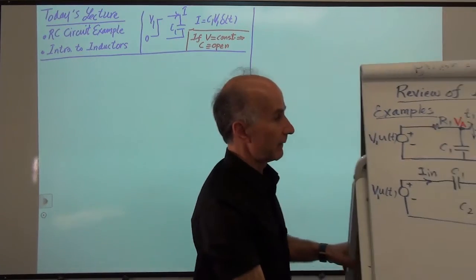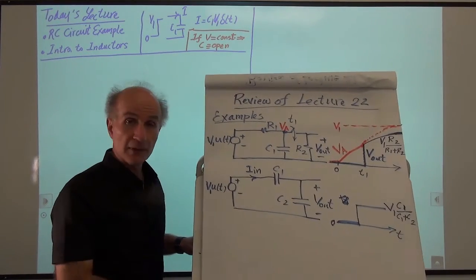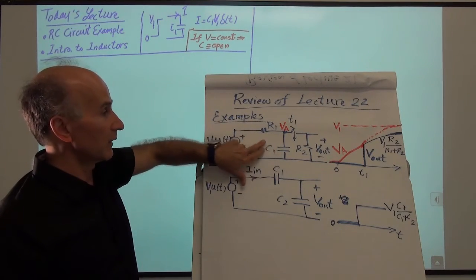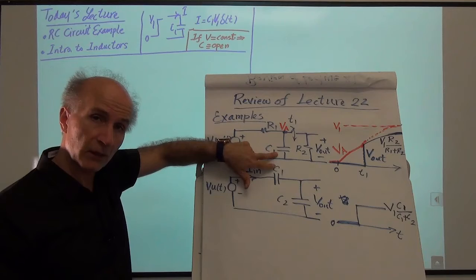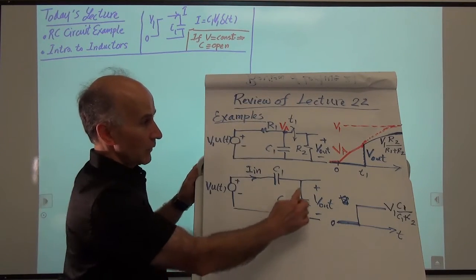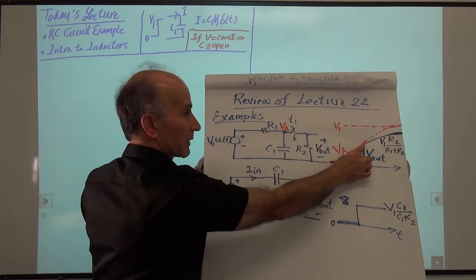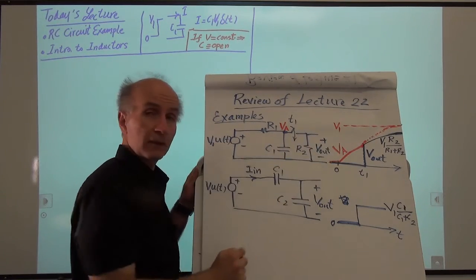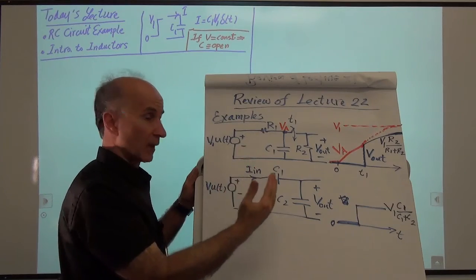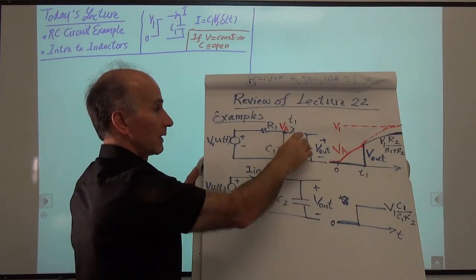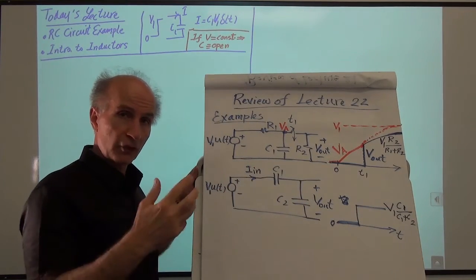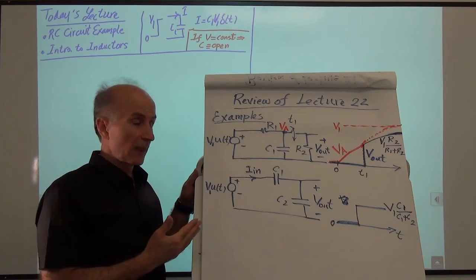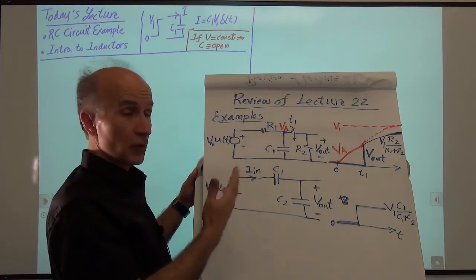We had two examples of RC circuits. We saw that in the circuit we first apply a step and let this capacitor charge to some voltage. So the voltage on the capacitor charges up to some value. It is headed towards V1, the maximum value, but before it reaches there, at some point T1, this switch begins to conduct and introduces R2 in parallel with the capacitor. As a result, now the circuit changes its properties.